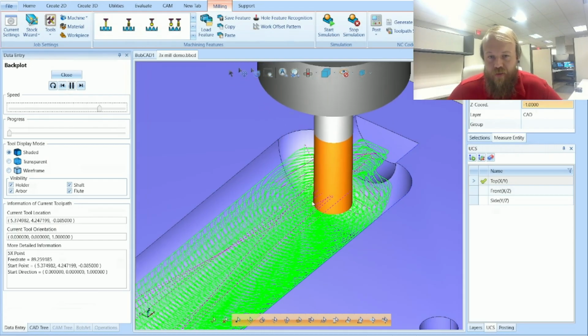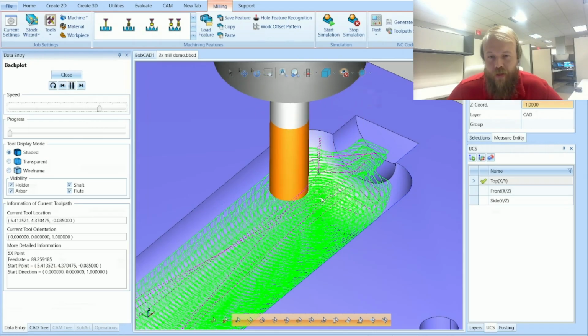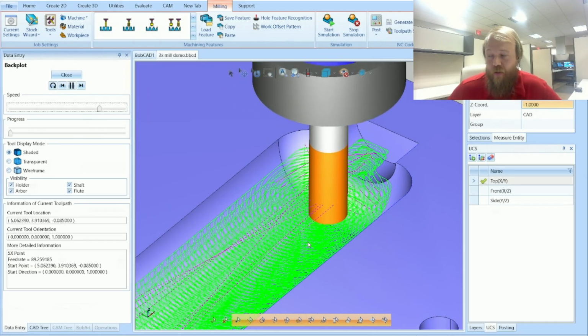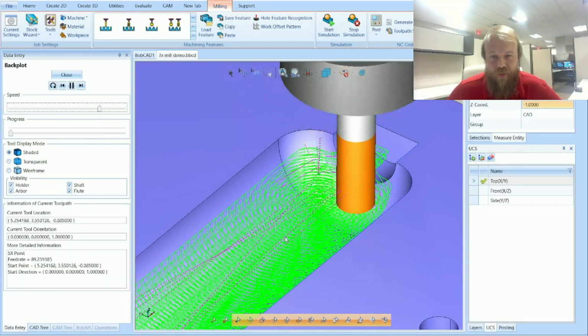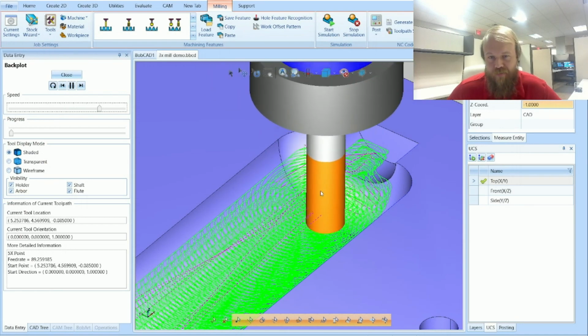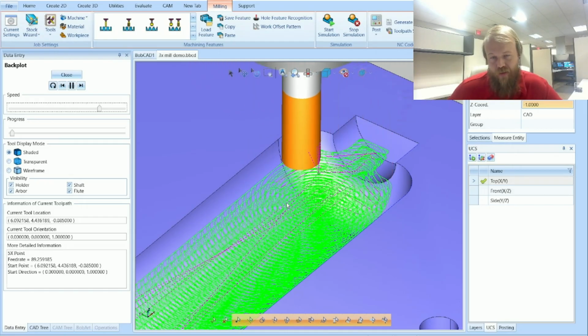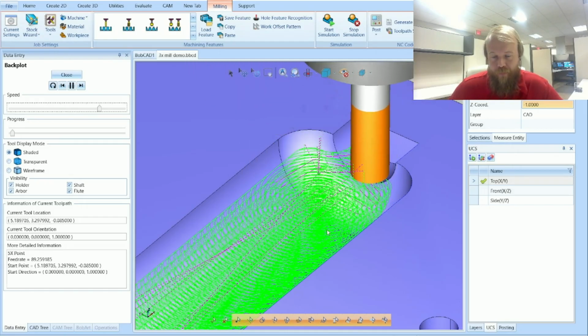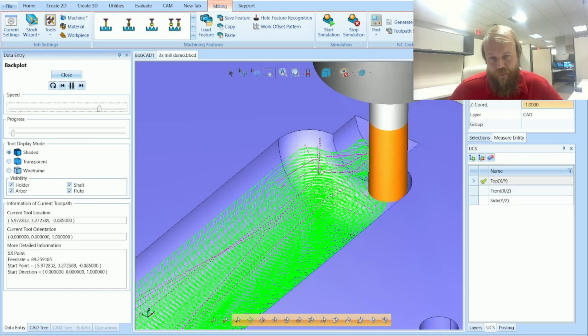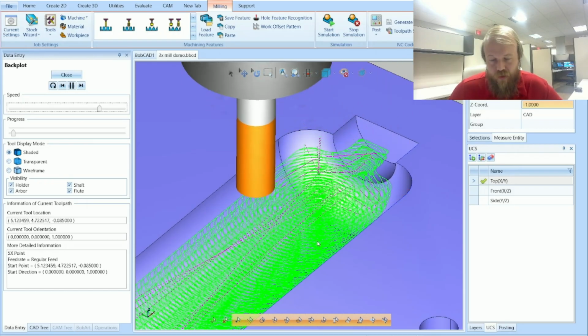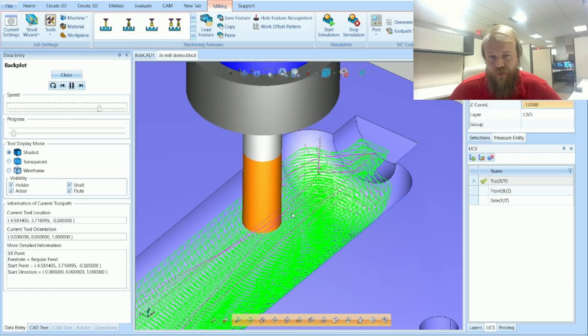So that's a good detail where the point has to be at the specific depth that you're going down to in this pocket, because maybe Bobcat thinks, okay, you've only drilled down maybe 1/4 of an inch and just do the first depth at that location. So you have to plot the point at the specific depth so that it drops down into that hole at every location.